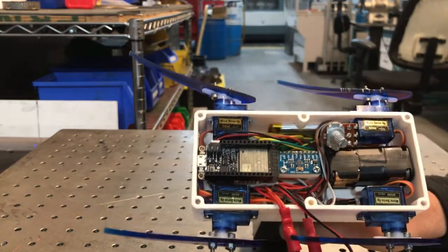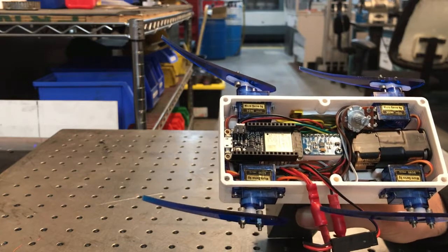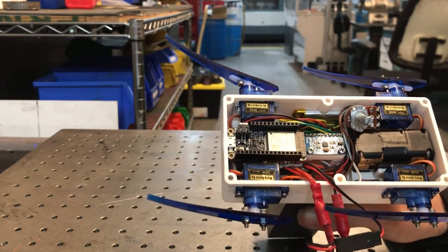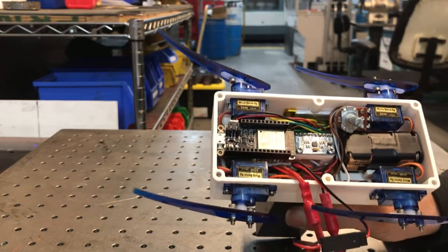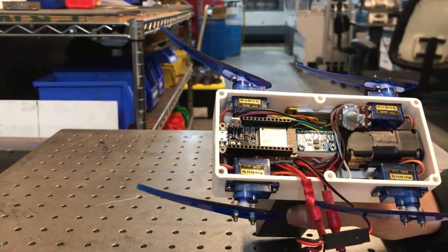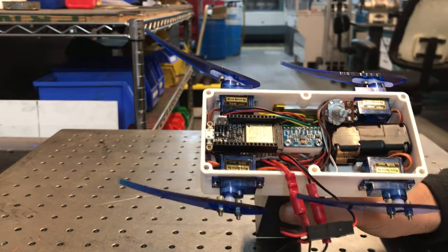So the first thing that happens when this device is turned on is it connects to Wi-Fi via a Wi-Fi hotspot, like on a mobile device. And then after that, it uses this Wi-Fi connection and then connects to the MQTT client for later data acquisition. After that, it calibrates bias error found in the IMU, and we'll talk about how we do that later on.